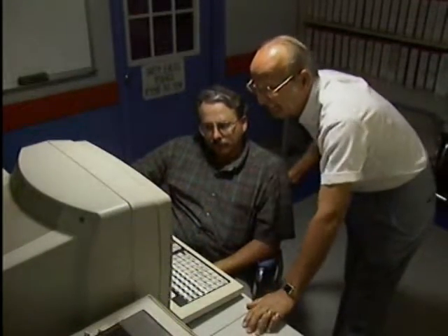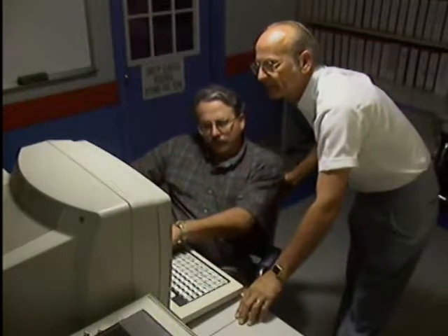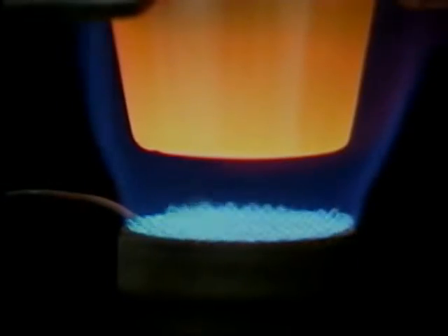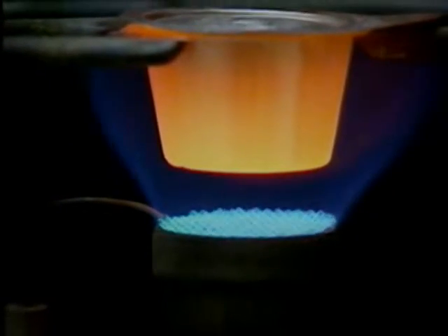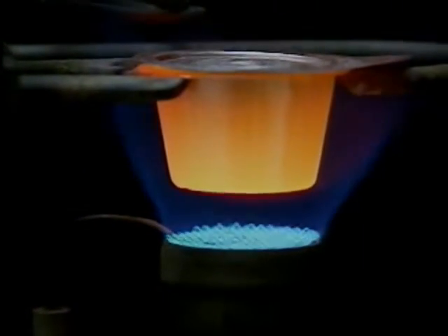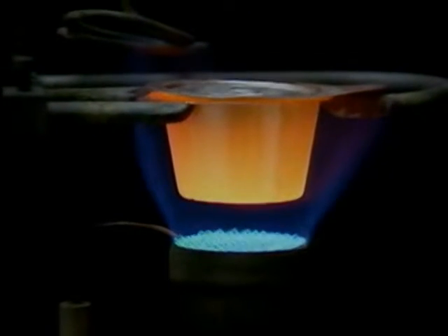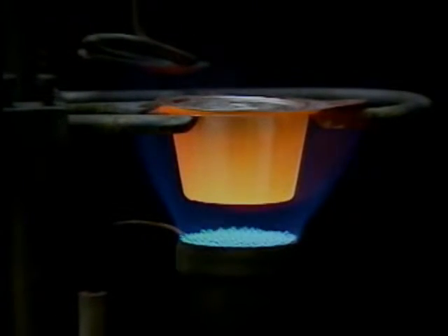but there is a possibility that the products leaving the column could be off-spec, and this could affect other processes. The control room operator has the feed material sampled and tested. The results of the testing indicate that nothing has changed in the composition of the feed material. This rules out the feed material as a source of the problem.